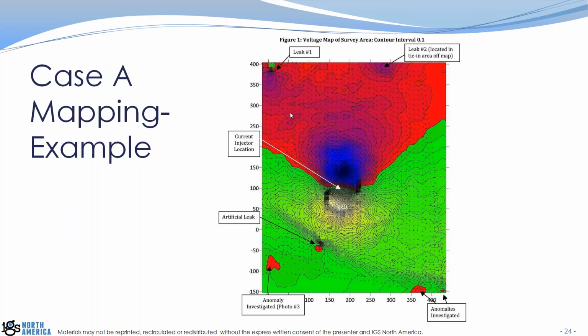So there's almost always some anomalies in the area because the cover material is hardly ever perfectly homogeneous. You will see leachate pipes. You will see any areas of ponding water. Sometimes puddles of water will give you anomalies. This whole sump area was basically standing water during this test. Anything where it's standing water in one area and fairly dry in another is going to look different.